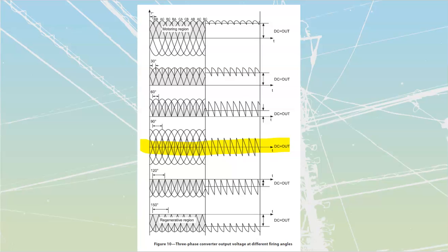If we reverse the voltage while still maintaining current in the same direction, we're going to have regenerative braking. And it's shown inside of here. It's a whole other set of lessons to go through just talking about regenerative braking. We've talked about it just on the surface, and we're going to keep it on the surface at this point because we don't need it to pass through third year. Just understand that anytime I've got reversed voltage while having forward current, I'm going to be able to create regenerative braking where I'm feeding power back into my supply. All right, that is it for this one.